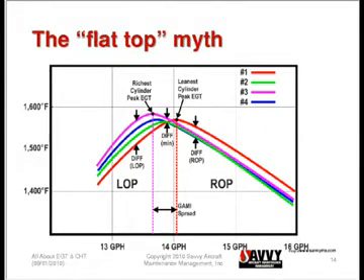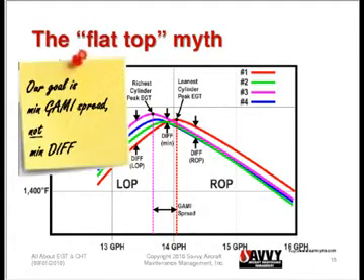pretty good. General rule of thumb is that we always want the GAMI spread to be less than a gallon an hour, and preferably less than a half a gallon an hour, for optimum efficiency and optimum lean at peak operation. The smaller the spread is, the further lean of peak we'll be able to lean this engine before it starts running unacceptably rough. So that's the GAMI spread.